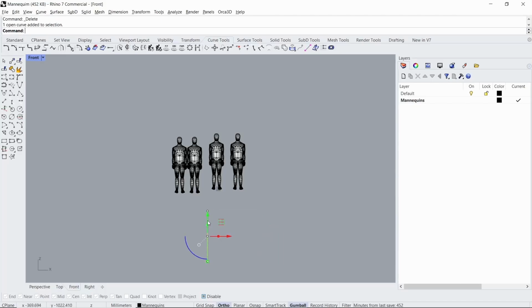Alternatively, we can click on the curve, press the arrow holding the button, and now we can press Ctrl. Once you have pressed Ctrl, we can see that the command for extrude that curve is being applied, and then if I confirm by clicking the mouse left button, it will create the same extruded surface. So those are basically all the commands that you can do in a much faster way when you use Gumball.